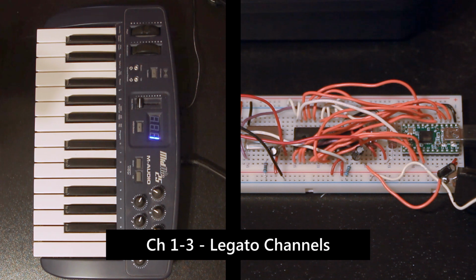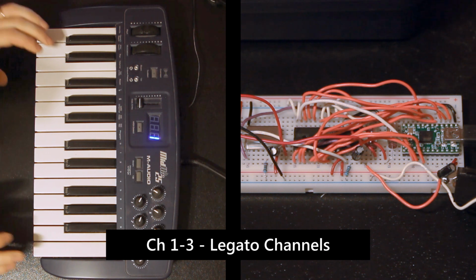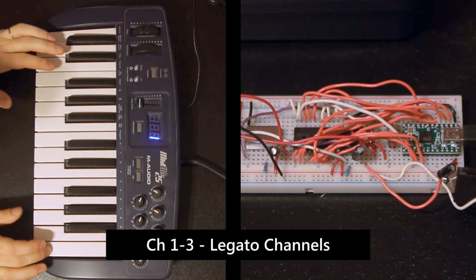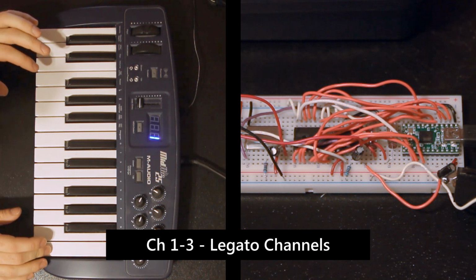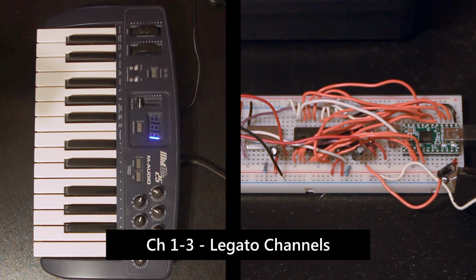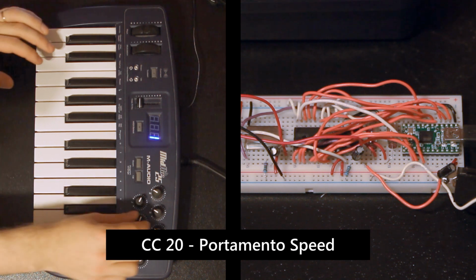MIDI channels 1, 2, and 3 control channels 1, 2, and 3 on the chip and are all symmetrical. Portamento legato is enabled on these 3 channels, so if you play a note without lifting up the previous note, it glides to the new note, instead of stepping to the new note. The speed of the portamento is determined by continuous controller 20.